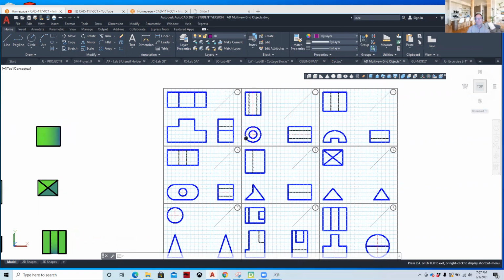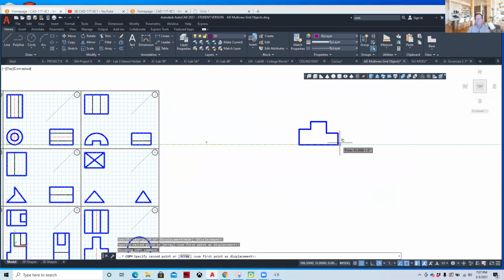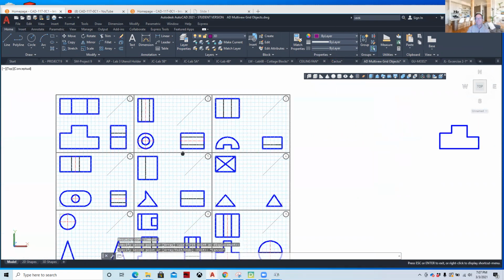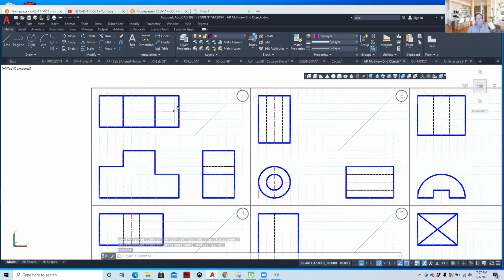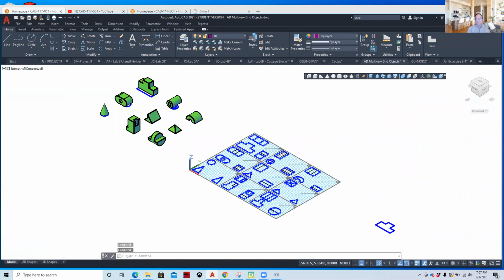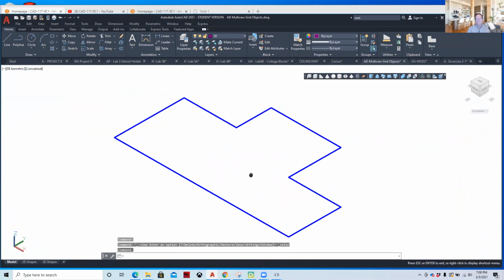And then if I were to model this part right here, what I would do is I would copy it from this endpoint, and then I'd establish a place out here on the side of the drawing in model space. I would go and take a look at how many units deep this part is. And so this is 1, 2, 3, 4. Come back over to our component, our widget, southeast isometric. And what I would do would be to press, pull, or extrude it.